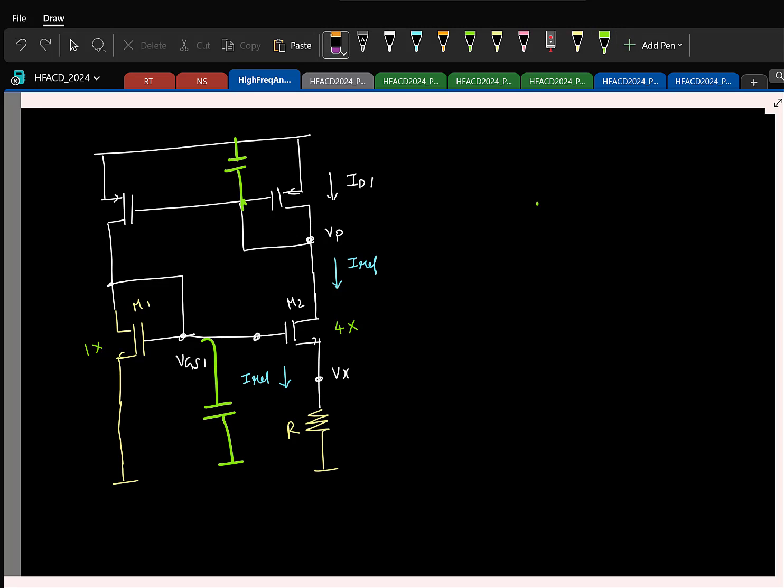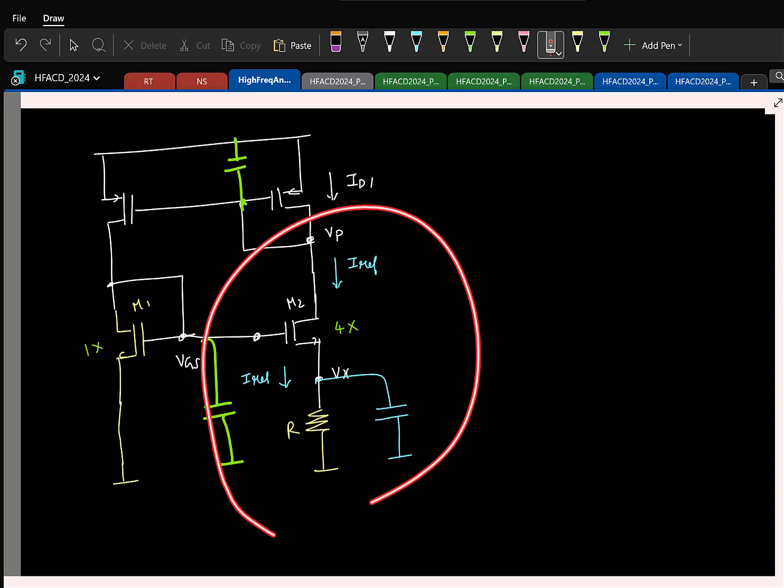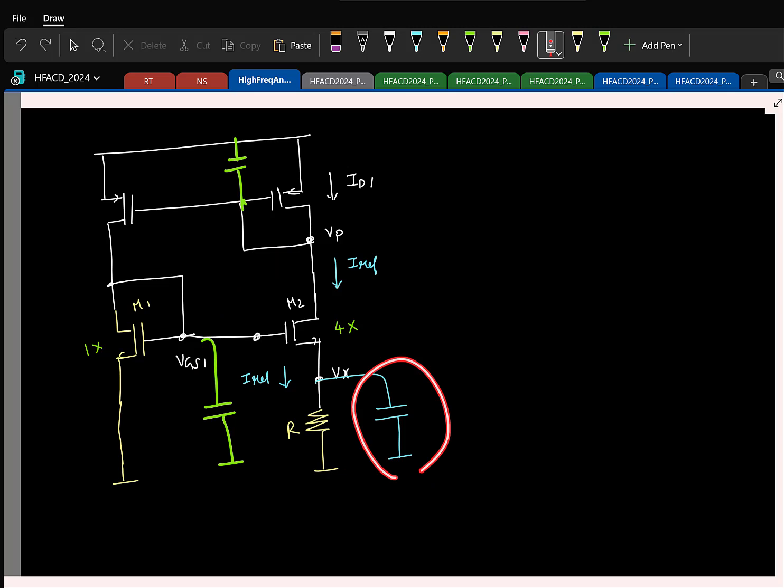And this is something people typically tend to overlook. In fact, this happened to one of my friends. He designed a chip, and this was a biasing circuit, and he had an off-chip resistor. And as a very careful designer, he put a large bypass capacitor on chip. Nothing worked. The entire chip didn't work, obviously. Biasing was not fine. For a few days, he was stuck. He didn't know what was happening. Then randomly, when we were discussing, we came to know about this. Once he desoldered the extra cap he put, the chip worked like a charm.